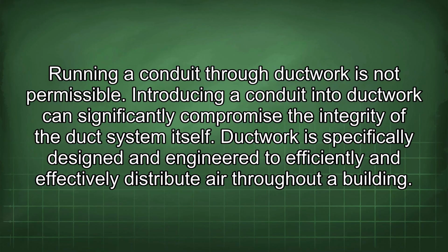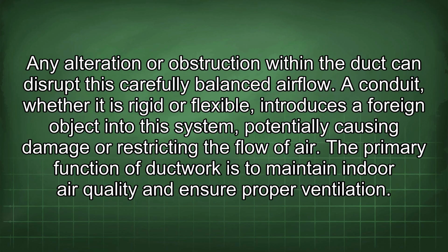Running a conduit through ductwork is not permissible. Introducing a conduit into ductwork can significantly compromise the integrity of the duct system itself. Ductwork is specifically designed and engineered to efficiently and effectively distribute air throughout a building. Any alteration or obstruction within the duct can disrupt this carefully balanced airflow.